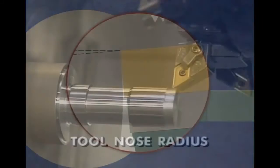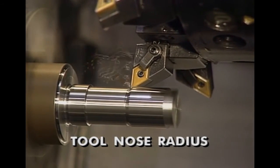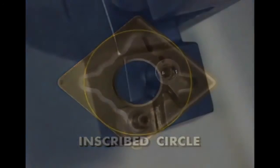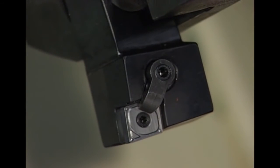The largest influence on chip flow in turning is the top or back rake angle. This is the angle created by the top of the cutting tool and an imaginary line drawn horizontally through the workpiece diameter. A positive rake cuts freely. A negative rake is stronger but generates more force in cutting. The tool nose radius helps determine insert strength as well as workpiece surface finish. Insert size is designated by its inscribed circle, and the inscribed circle size of the insert must match the pocket size of the tool holder.